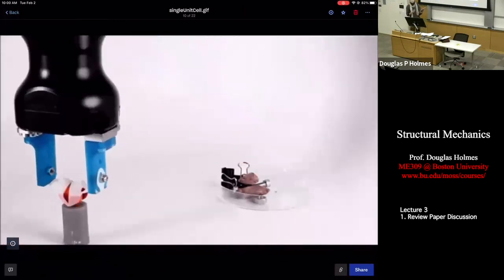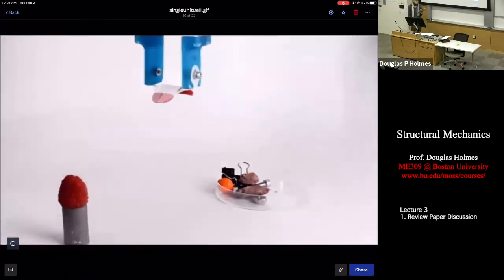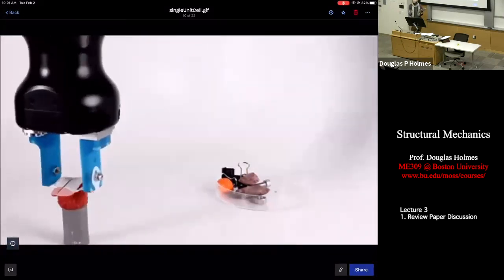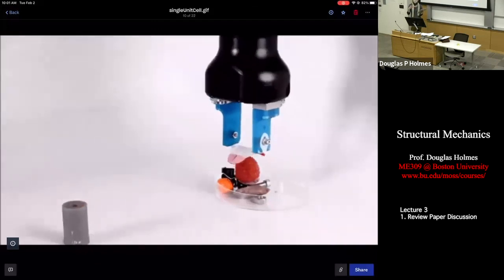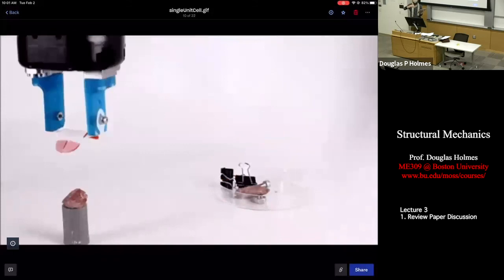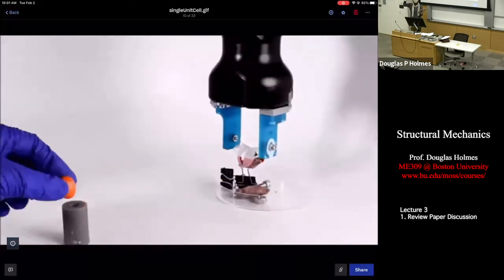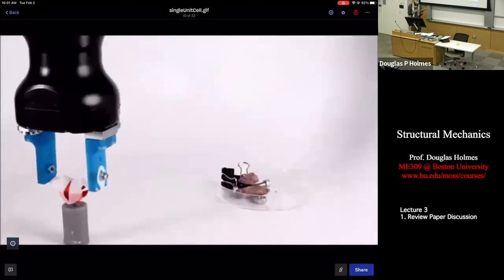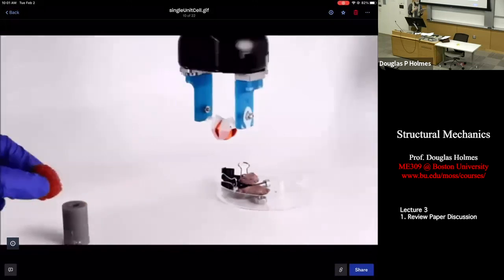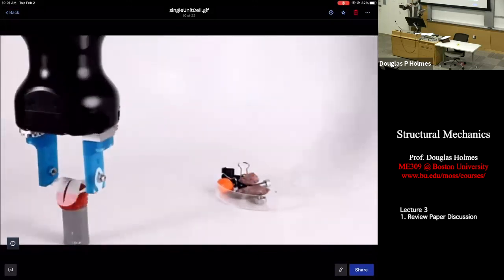This is the sheet we made in our lab. It's attached to a robot. All it is is a sheet of plastic, mylar. Doesn't really matter what the material is. We put cuts in it in a certain way, and we warp it into a cylinder. And then if you pull on it, it makes a really great gripper. It can pick up a ton of things. It's picking up an M&M, picking up a raspberry without squishing it.